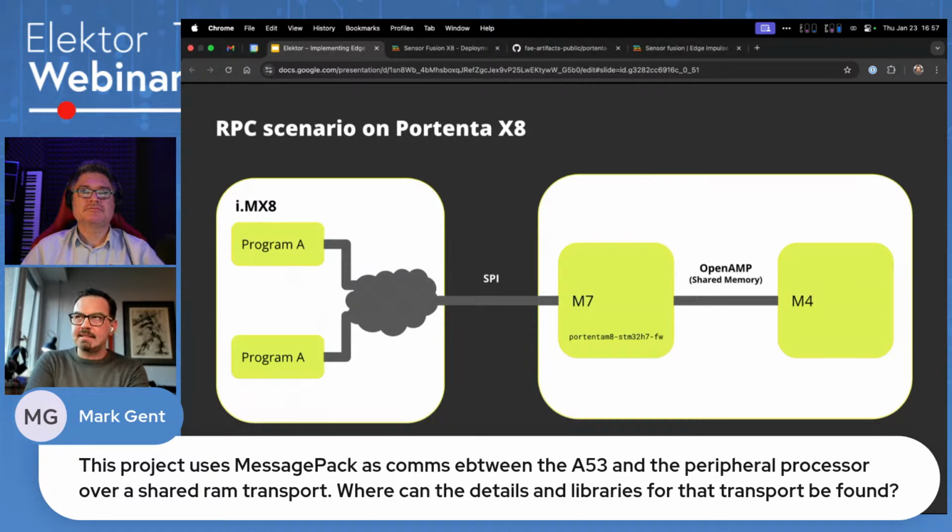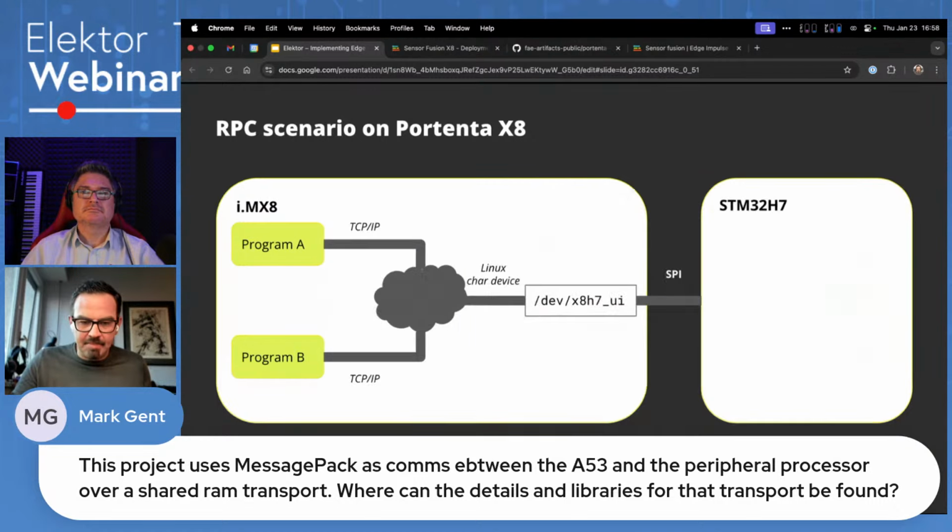that allows us to share a few specialized peripherals such as CAN, I2C, SPI to the Linux microprocessor, and then this firmware relays the request from the RPC to the M4 core. From the M7 and the M4, we are using a shared memory technology based on OpenAMP.